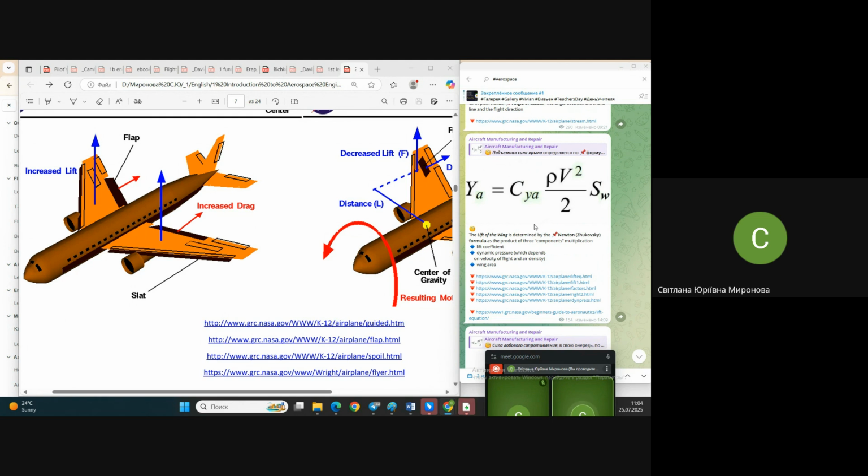During takeoff, they are moved down significantly, but not completely. Some middle position, approximately 10, 12, 15 degrees for flaps. And when it comes to landing, we are interested in very high drag, in order to reduce the runway after touchdown and to stop the airplane quickly.